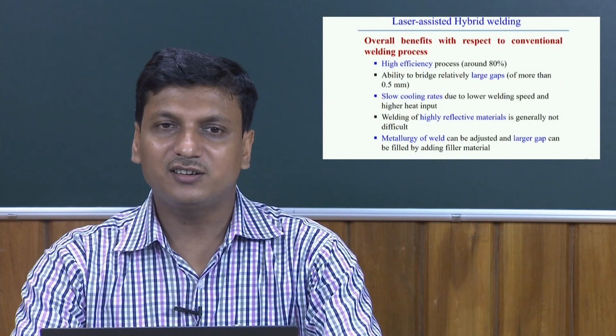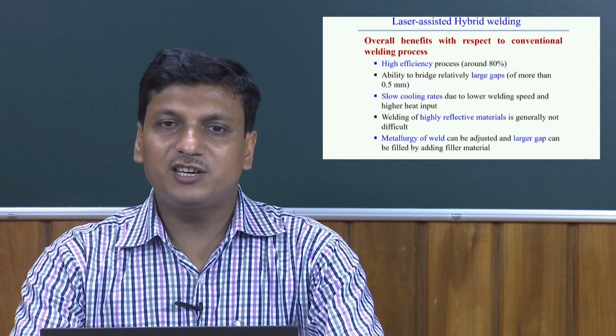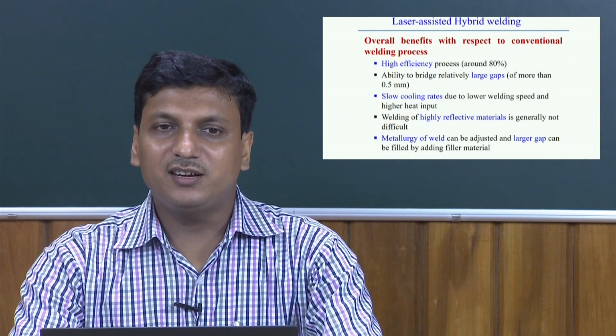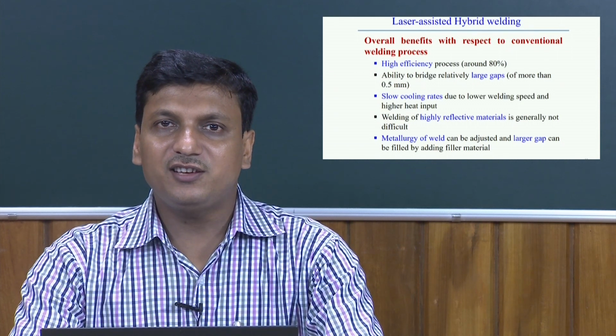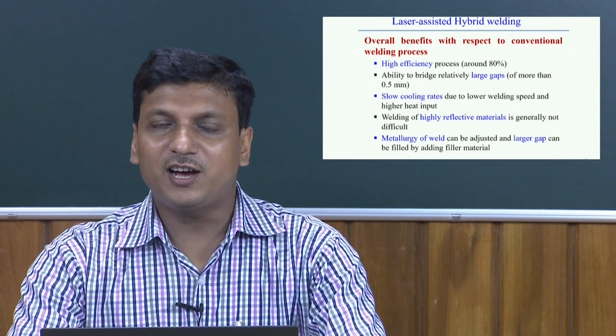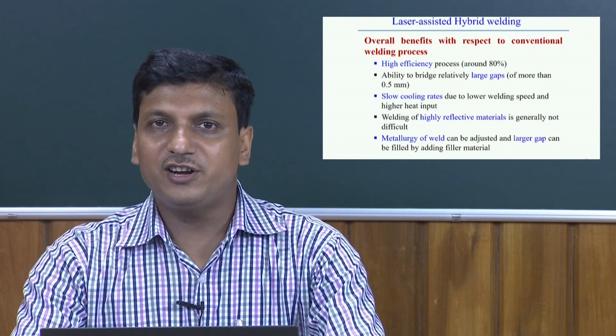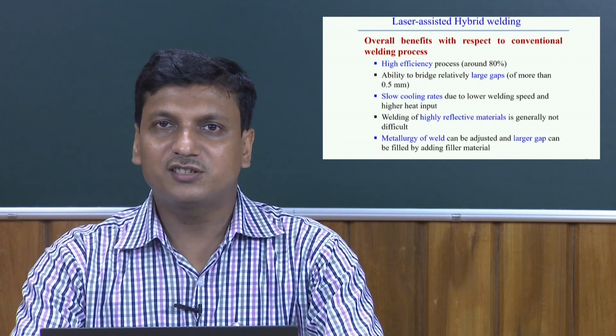Another advantage is the slow cooling rate. If we use a relatively low welding speed, in that case the heat input per unit length is very high. So, in this case the rate of cooling is very slow.